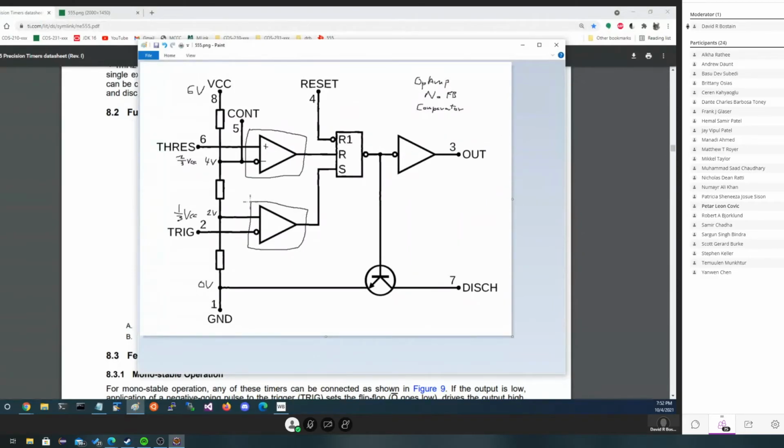Now let's assume for a second that the trigger pin has 1 volt on it. What's the arithmetic being done right here? Who can tell me? Scott, what would it be? So we're going to be comparing plus 2 volts in to the minus 1 volts at the bottom. And so 2 minus 1, so is 1 volt. Yeah, we get 1 volt, but since it's operating now, 1 volt, is it a positive or a negative number? It's positive. Since it's positive, this goes to full positive.